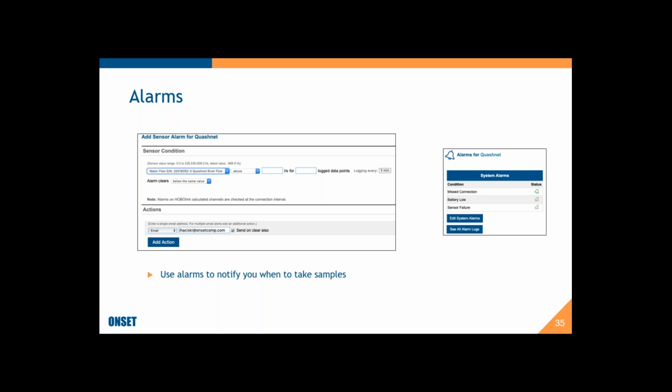I'm just looking at the questions again to see if there's any I should touch on now. Let's see, can our hardware be used to measure flood irrigation inputs and runoffs? Oh yeah. If you are measuring flood irrigation, you can put a weir at the end of the flood irrigation, or at the input of the flood irrigation, as a way of measuring the water coming into that. That's, I think, pretty common to do.